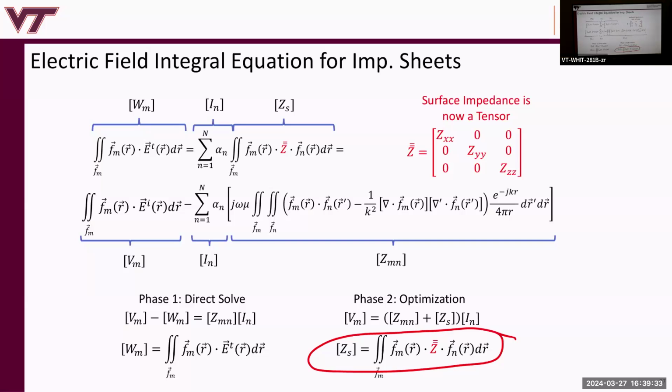All right. The reason why I started with this diagonal impedance matrix is because there's a step that's not shown here. Step 1 here is to solve this direct matrix equation by stipulating what the total electric field is, right? But then you have to solve for the sheet impedances after that, which you guys did in your 2D homework, the last homework. In the last homework, when it was a 2D problem, E tangential or E total, these are scalars because it was one polarization, TE. We did TE, right? Yeah, TE. J surface, these are all Z-directed quantities. To find the sheet impedance, you just divided these scalars, right?